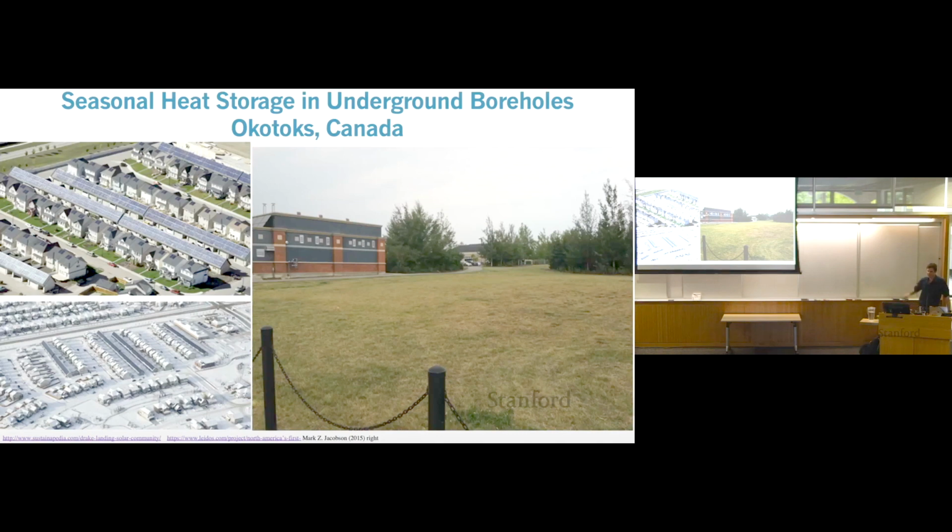This is just a play field that had been excavated, and these boreholes were drilled about 30 meters down, and U-shaped pipes were put in. So the hot water goes down, and the heat is transferred to the soil to heat up the soil, and then the water comes up cooler, and then the water goes back to the building to get reheated. But that heat is stored for up to 6 months in the soil, and the soil temperature can get up to 80 degrees Celsius. But on the surface, it's insulated on the top. On the surface, you can't feel it, and you don't even know there's a storage system underneath. In fact, there are kids playing on this field.